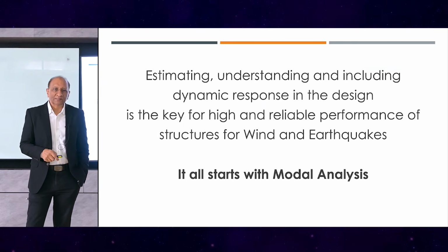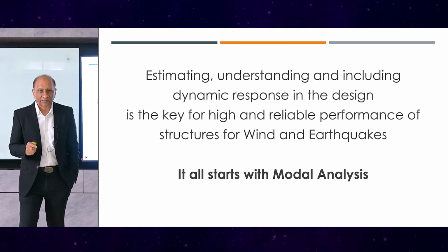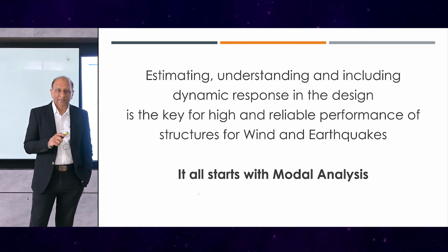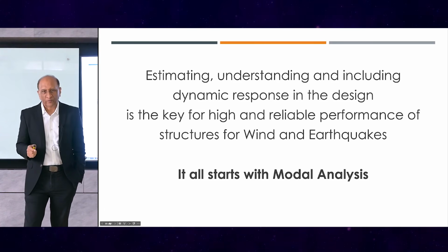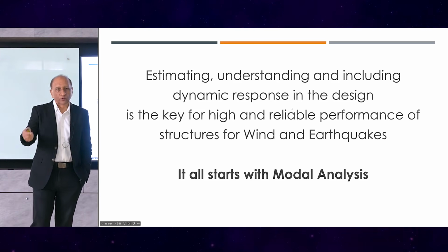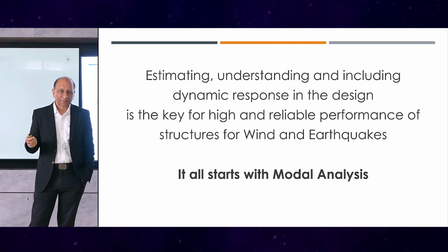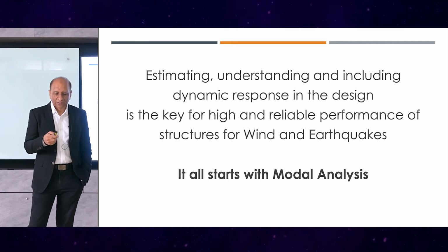So let's conclude by saying that estimating, understanding, and including dynamic response in the design is the key to the reliable performance of structures, both for wind and earthquake, and also for floor vibration, walking, and all that kind of stuff, even blast. But it all starts with the modal analysis.